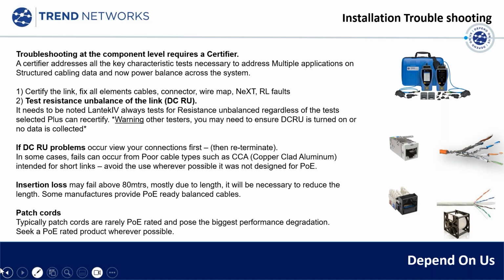And it is only a certifier that can do that. So I just want to confirm a certifier is needed in the latest test requirements. Okay, so step one for troubleshooting is, of course, to certify the link. And we're going to look at all the elements, the cable and the connectors, okay?